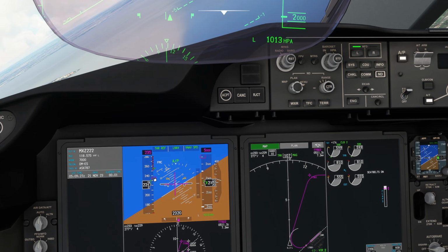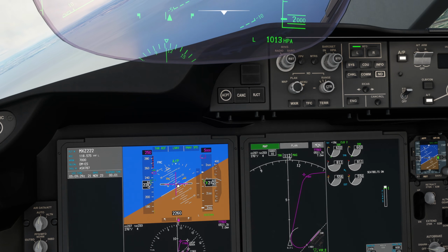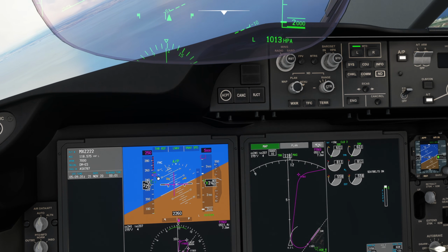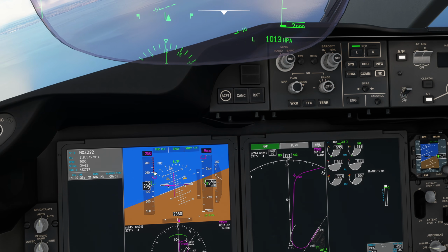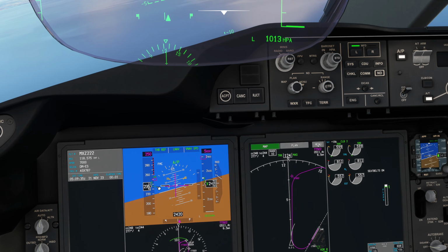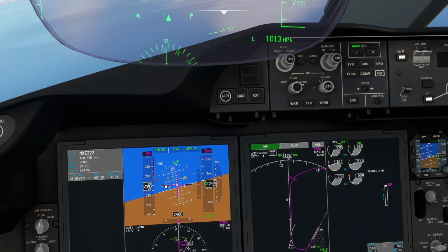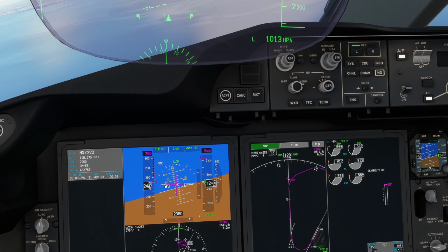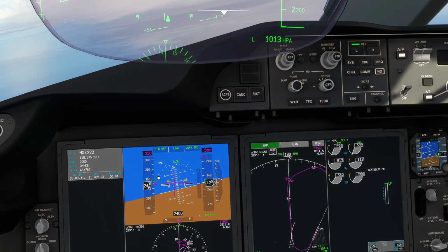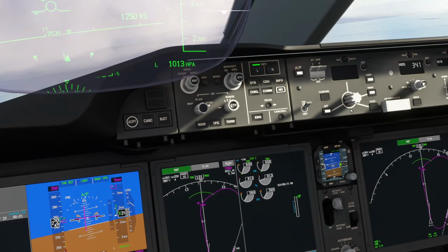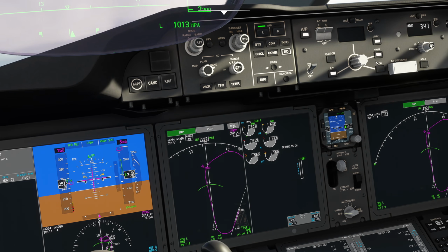Once we get above the 1, we can set it to up. There you go, you can see it's actually below the up speed, but that's not a problem, it's just giving itself a margin to the flap limit. So as we go above 1, we set up. And on the real aircraft, it would actually clean itself up to a suitable speed. This has kept us a bit slow.